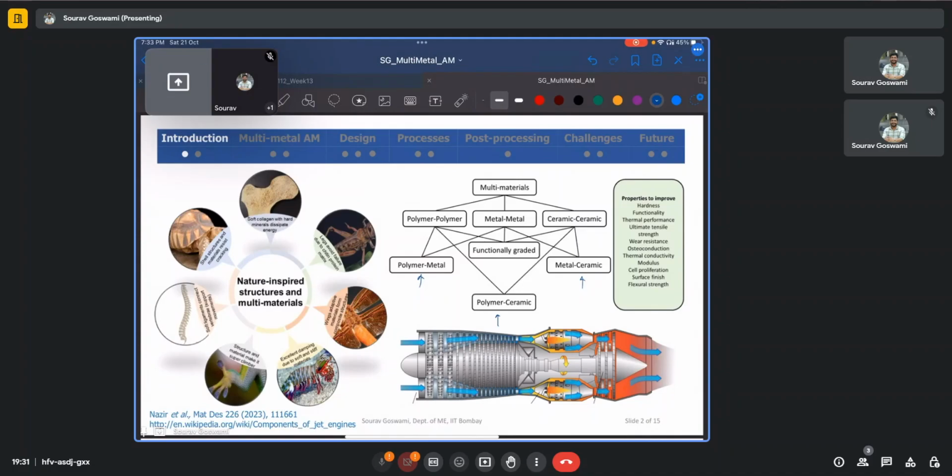machine. Say in the combustion chamber, on the hottest regions, we can have parts made out of Inconel, whereas in some of the other regions they may be made out of stainless steel. And the key thing would be to avoid any joints or any sudden sharp discontinuity in the material combination or the material gradation from steel to Inconel, as that would be the site of all defects or failures. And that is where the functionally graded materials come in.